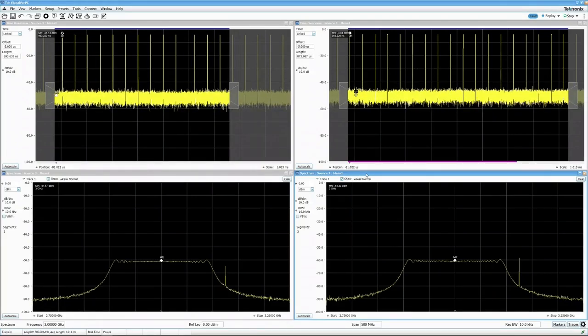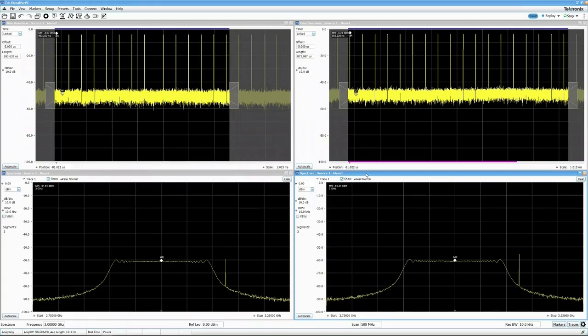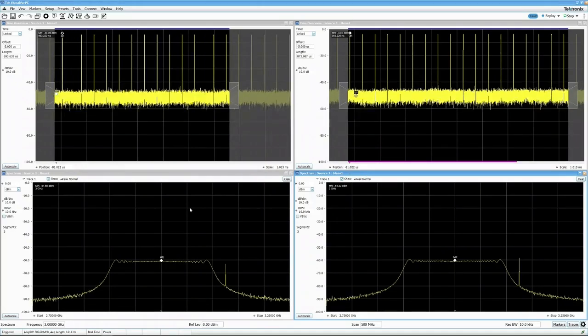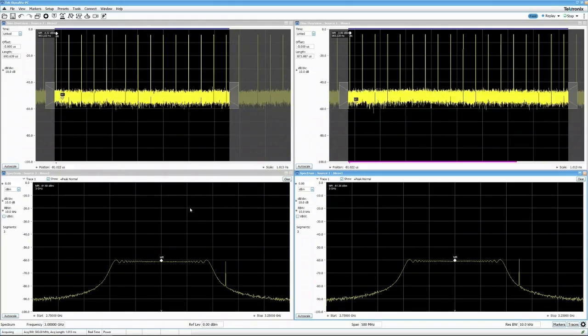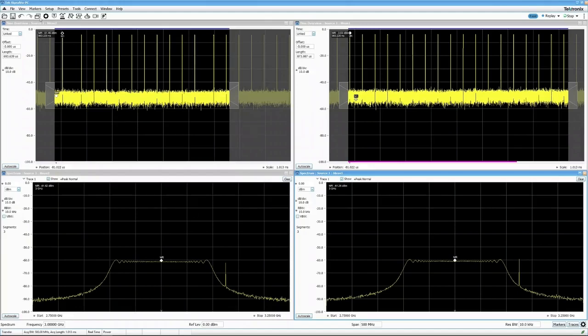Channel 1 of the AWG is connected to channel 1 of the scope and is used to simulate the radar transmitter's output. Channel 2 of the AWG is connected to channel 2 of the scope and is used to simulate monitoring and calibrating the echo target simulator's output.